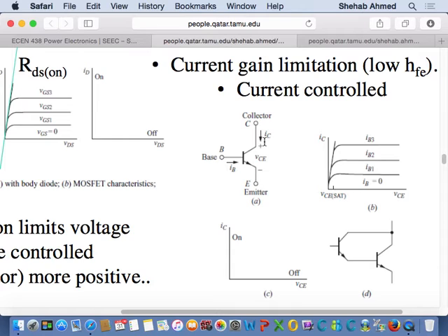If VCE is negative, it will not function properly. In 325, you were going through and making sure that you were creating a collector voltage that's higher than the emitter voltage for current to flow. Remember, you were doing the bias circuits in 325? You were building all these resistor circuits and looking at voltages across the devices, from collector to emitter, emitter to collector.